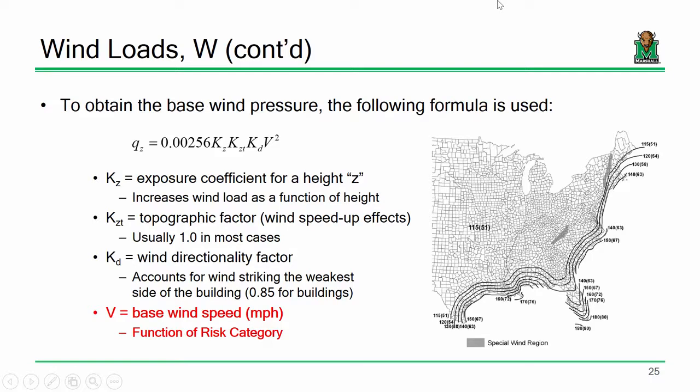How does Bernoulli's equation work? You have point 1 and point 2, and they each have different properties, and you're solving for one. So if you have the pressure at 1, what's the velocity at 2, right? You all remember that? Well, the way this works for wind is pretty straightforward. We treat air as if it's our fluid, so we would use the unit weight of air like you would use the unit weight of water in Bernoulli's equation. We have 2 points.